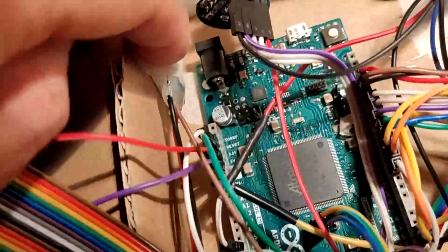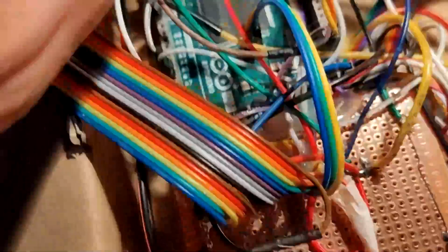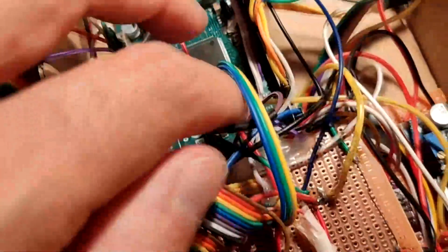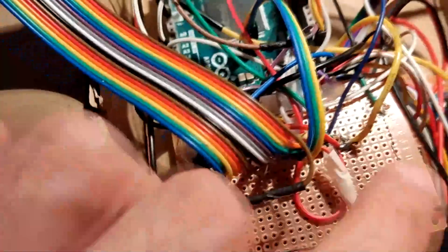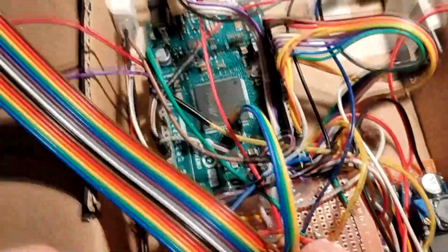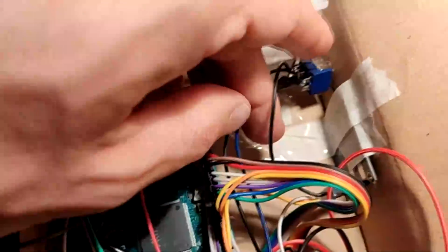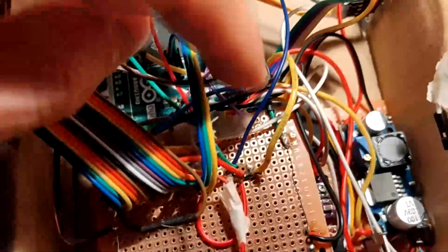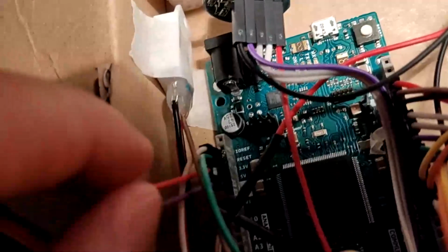One thing I forgot is the DHT22, with the ground connected here and the 3.3 volts connected on the big drop of solder. We have the rotary encoder soldered on it. You have the yellow wire here for the optocouplers. Here we have the blue wire for the switch, powered with 3.3 volts. And all these wires are connected by this green wire to the 3.3 volts of the Arduino.